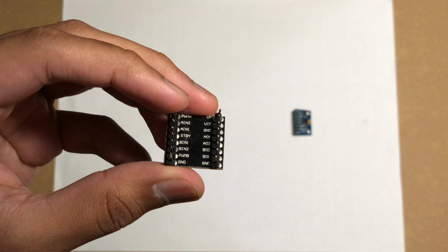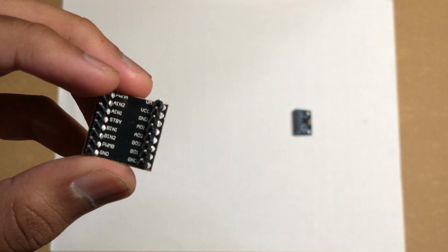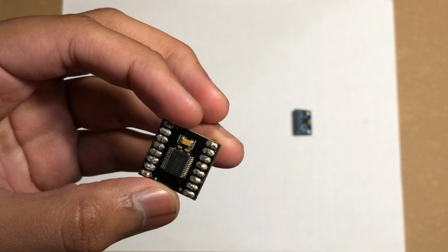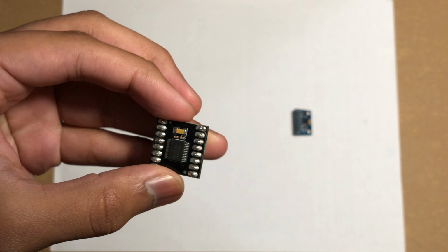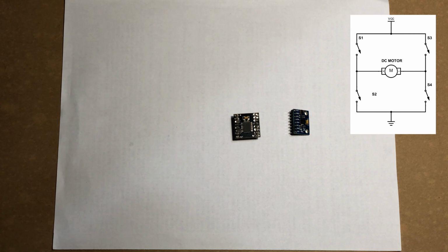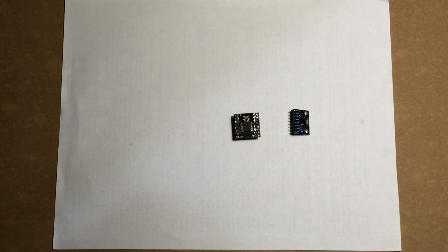The TB6612FNG is a dual motor driver which is ideal for integrating two small DC motors to a microcontroller, and it can also be used to control a single bipolar stepper motor. It works based on the H-bridge concept but is more efficient, and it allows more current to be delivered to the motors and less current drawn from the logic supply.